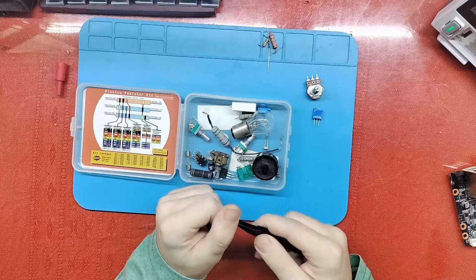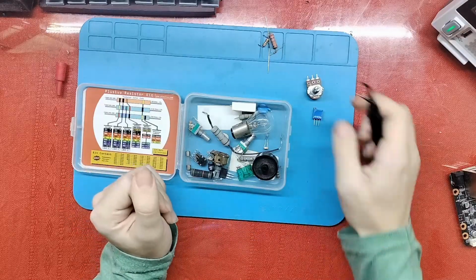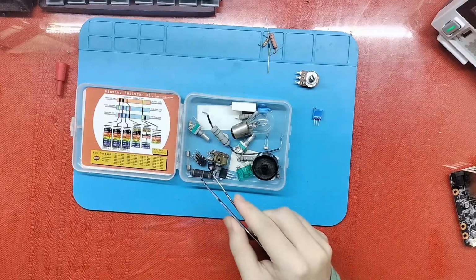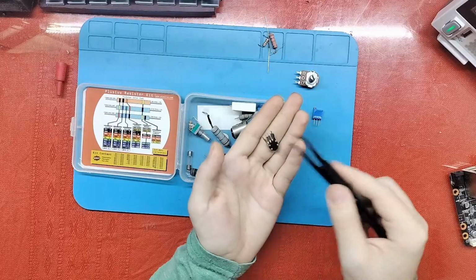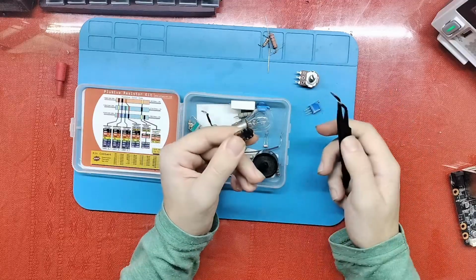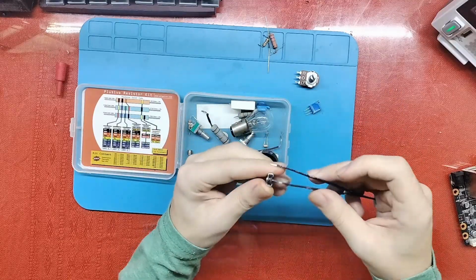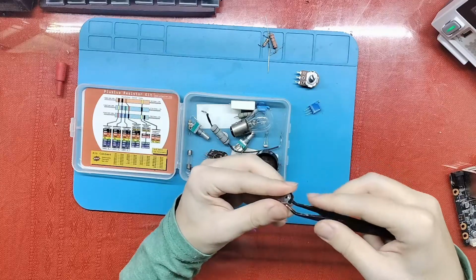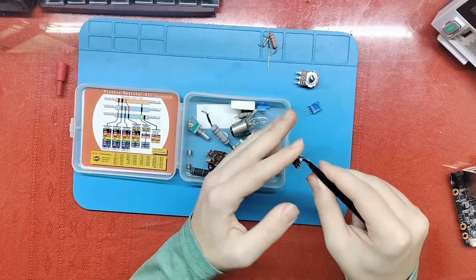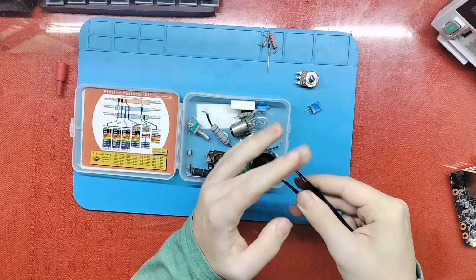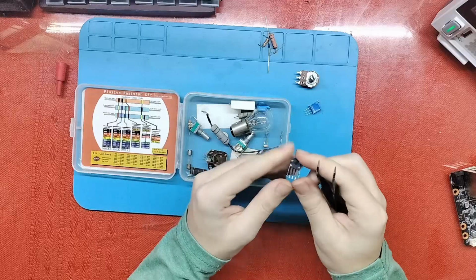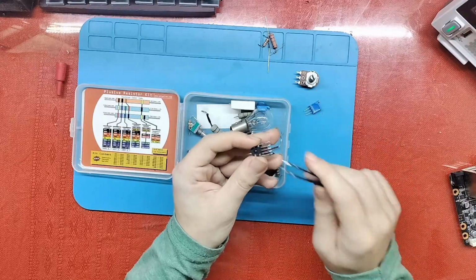Now, there are imposters that look like this but aren't actually potentiometers. And the imposter, it's this one. You may think, oh, it's just a different package of potentiometer, but no. If you spin it, you will see it spins constantly. It doesn't have an end. You could go like this for hours on end and you will not find an end stop or anything. This is a rotary encoder. It still has 3 pins.